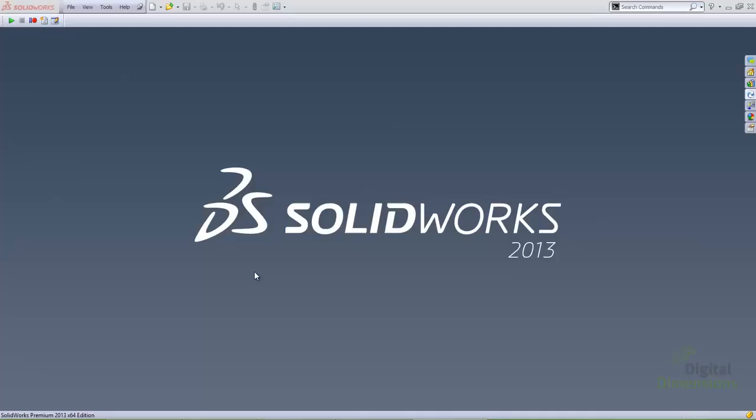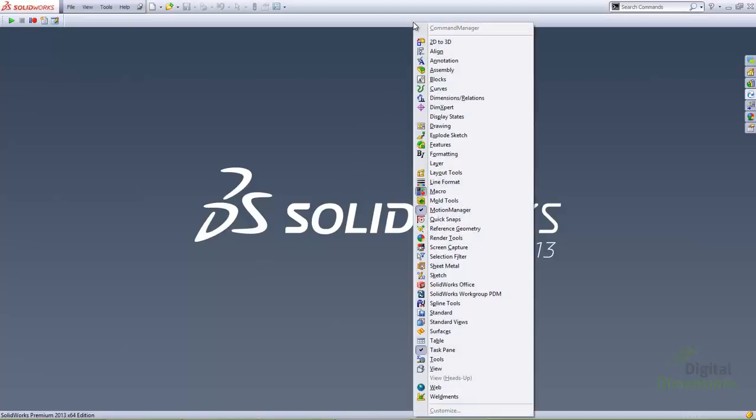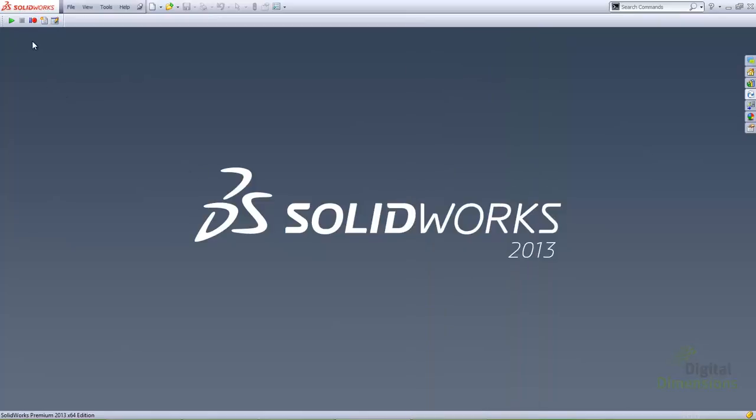There are a few things I want to point out before we actually start an example. The first is this macro toolbar that we need to have on in order to record macros. By default, it's off, but if I right-click up here, you'll see an option for a macro toolbar. You'll want to make sure you turn that on before we start anything. That's the main toolbar we're going to be using. That's where we go about running, creating, recording, and editing macros.